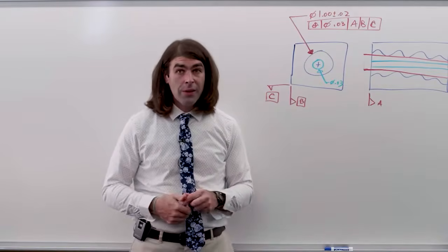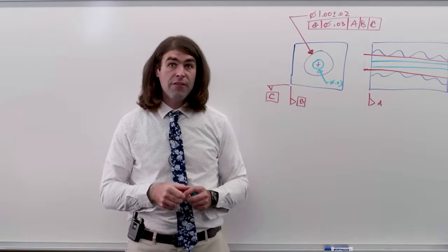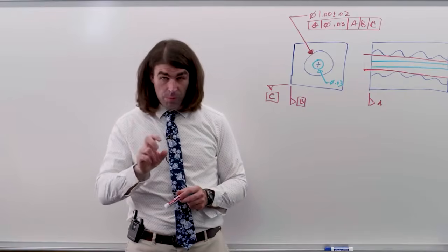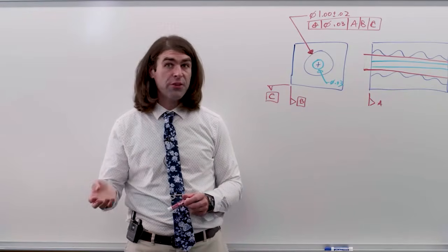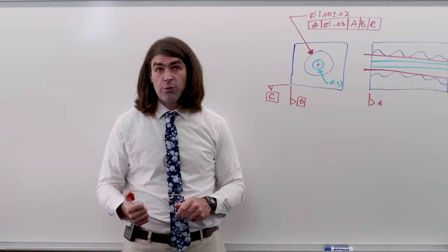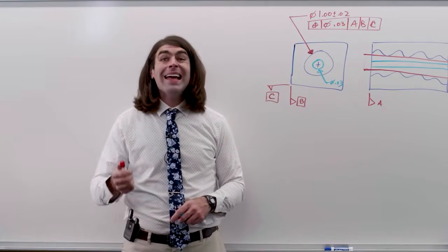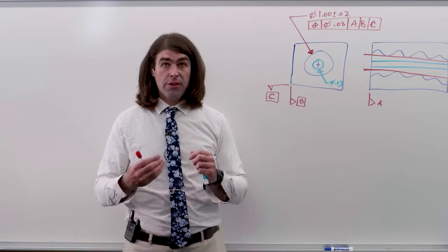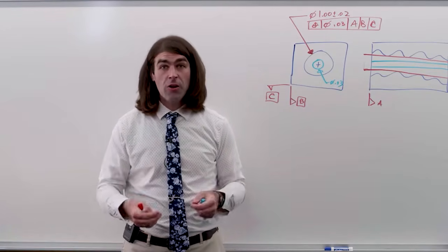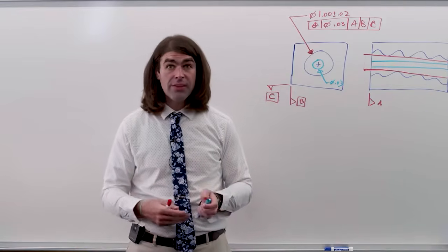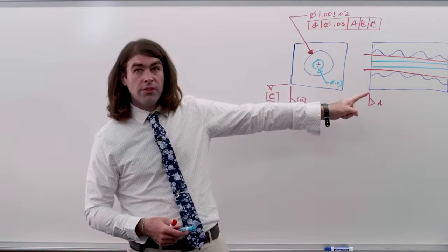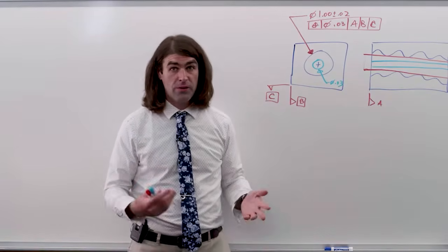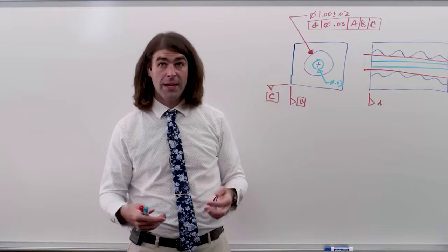Okay, so imagine we went through our box of gauge pins and we found the one that will fit through just barely, and it won't wiggle around, and then the next size wouldn't fit. That's our actual mating envelope. The axis of that is going to be the axis of the feature, right? Because we only care about these high points, because when this part goes into service, those high points are going to be what's going to stop something going through the hole, whether it's a pin or a screw or a bolt or a mating part.